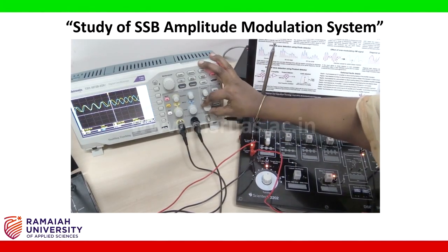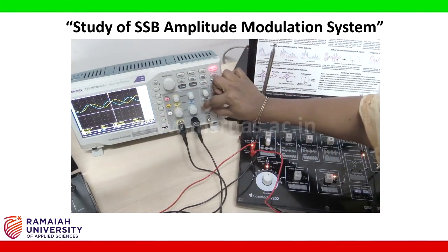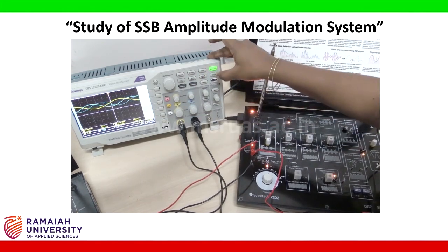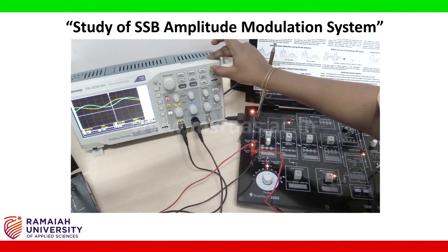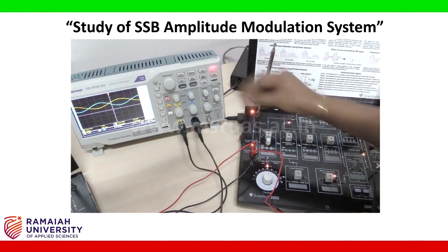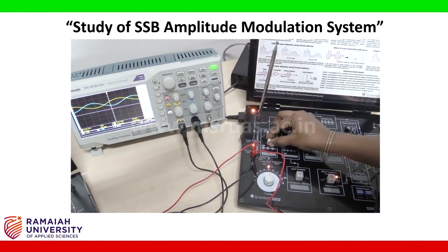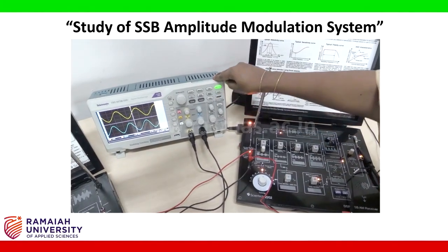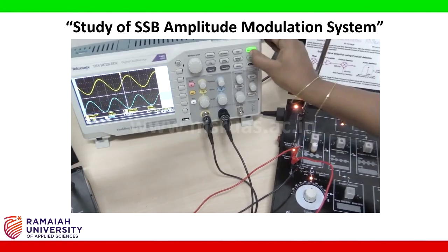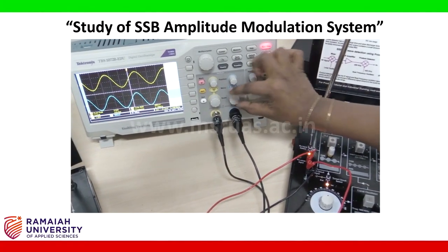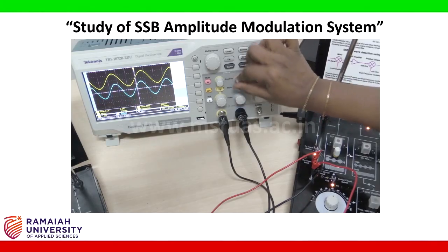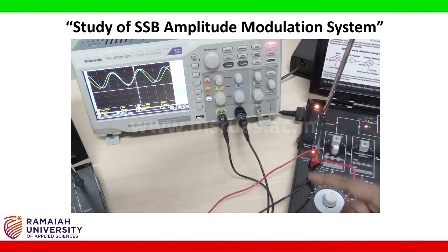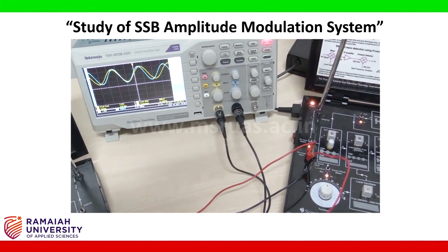However, you can adjust the time scale and verify. Press auto set and you can overlap the waveforms. Try tuning. As you tune, you can observe that the input message and the demodulated message are almost the same.